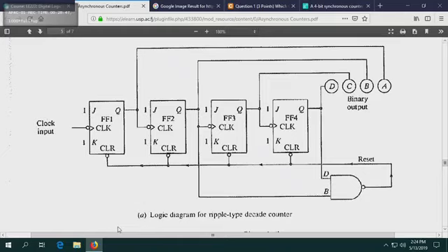Simple. Right? Okay. Now, what about your T? How can you make your T flip-flop toggle? Can you see your excitation table? What can you do to make it toggle? Your input has to be 1, right? If you make input 1, it will toggle. If you make input 0, what happens? It's in memory mode, yeah? Is that correct? Okay, T is only 1 input. So again, you're just using a 1. Now, what is happening over here? It's a ripple counter, I can tell you that. It's a ripple counter, right?